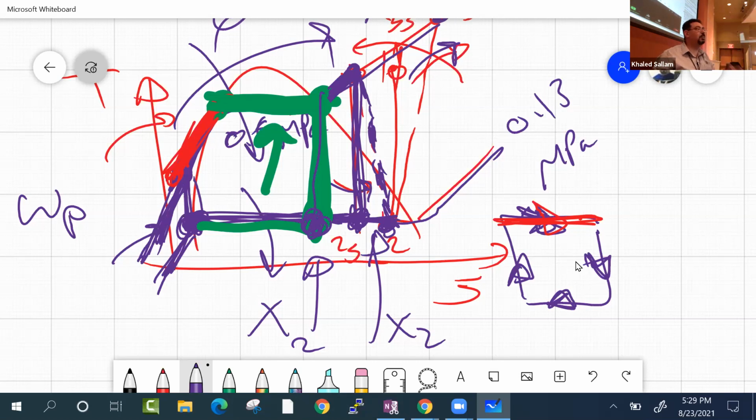It's pitted. You put your hand on it, and oh my God, you feel the agony of that turbine being hammered, basically shot at all its life with small droplets at very high velocity. So you want to make the turbine dry, and that's why you need to go up, then expand like this, so that you don't end up with very wet steam.